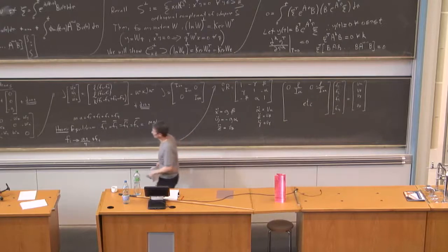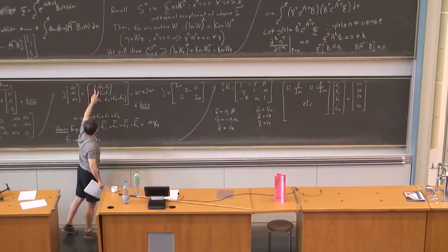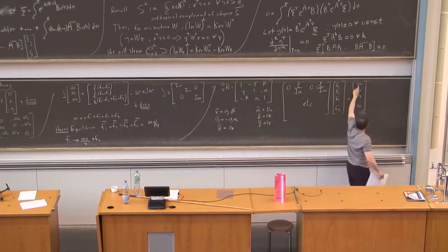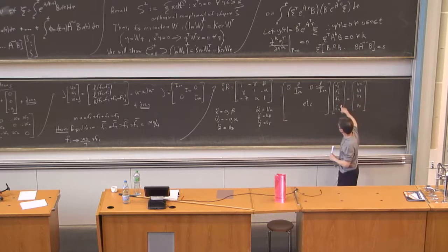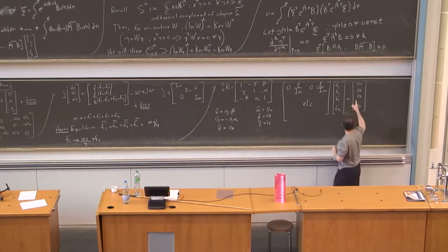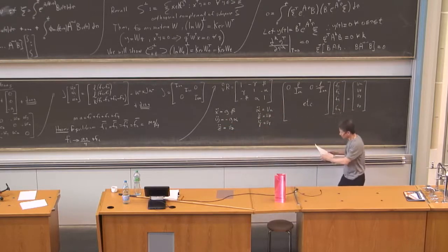It's basically just take these equations here, and I want to define these new control inputs. It's easier to write it in this way instead of keeping my original F's. I do a transformation. This is just a 4x4 matrix. It's invertible. It allows me to solve for the u's in terms of the f's, and allows me to write the simple equations in this form.